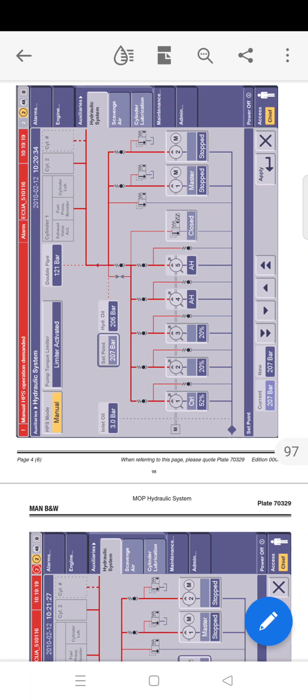So this ensures oil return to the suction side of the pumps and thereby avoids cavitation and unintended wear of the pump parts. Also, sometimes the shutdown happens due to oil pressure falling. If there is a leakage, the servo oil pressure will fall and the engine will continue to turn due to windmilling, and this time the pump will continue to deliver oil to the delivery side, and all the oil will go outside due to leakage. So this amount of oil spill can be reduced by leading the oil back to the suction side. So that is another advantage of this bypass valve.